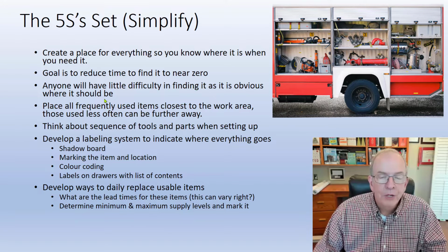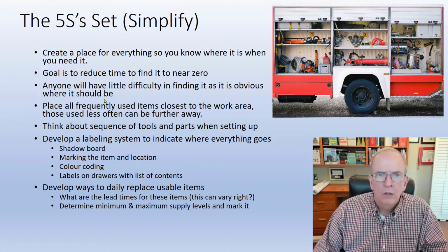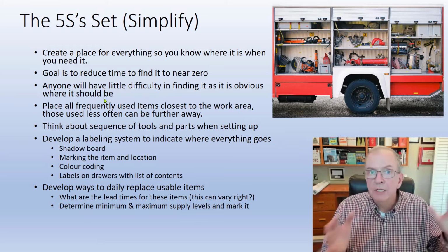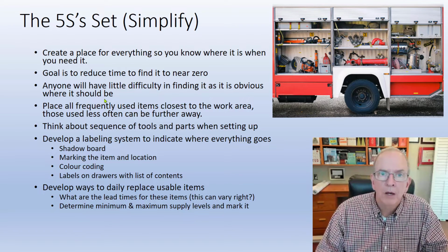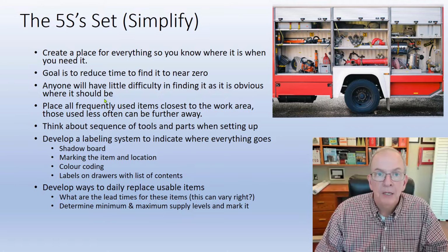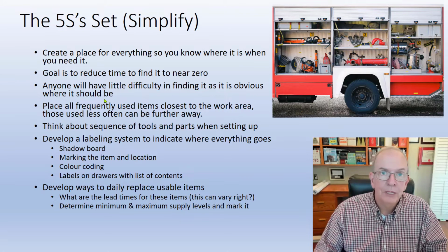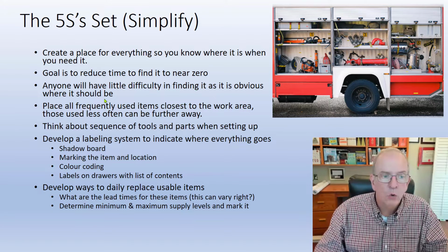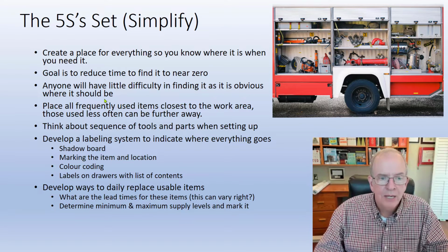So have frequently used items closest to the work. This is a big thing in construction. So you're doing a multi-floor condominium. Well, what's the stuff you're going to need frequently? Make sure it's on the floor that you're at. What's the stuff that you need infrequently? Then you maybe are going to have it in a C-can box down near the bottom near the trailers. But you don't want to have the stuff that you need frequently there and you're going up and down and up and down and up and down the material hoist. So you've got to organize yourself so that you can access it depending on use.